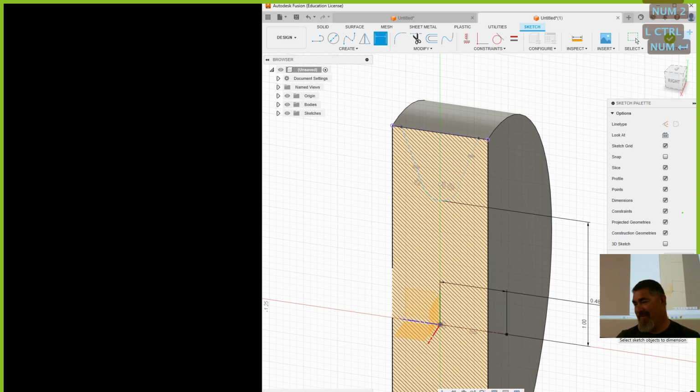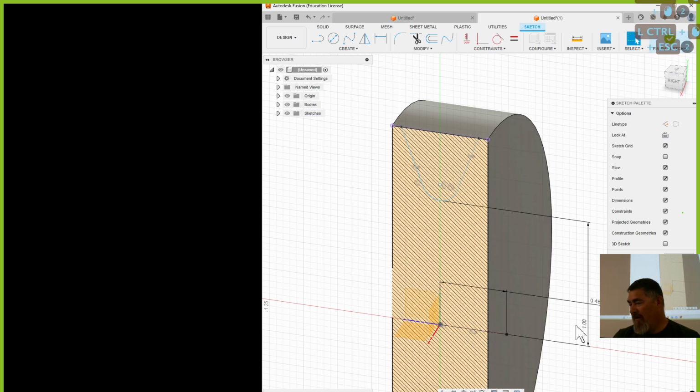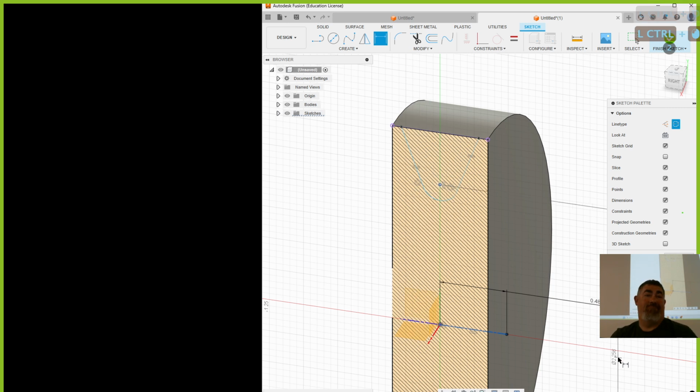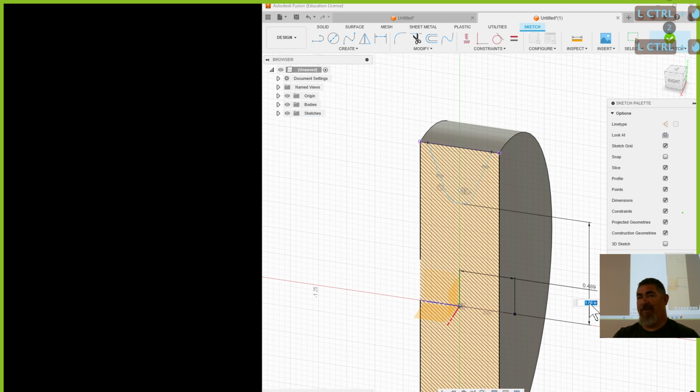When I do that, I right click on whatever the second line is, and then it appears to change it to diameter dimension. Yeah, but if for some reason it's only giving you the radius, I don't know why. Oh, that's because I went to the tangent. Going to the center, it's giving me the diameter. It must be just when I do the tangent that it gives the radius. So it kind of overrides it in that case. So then just put in the diameter divided by 2.